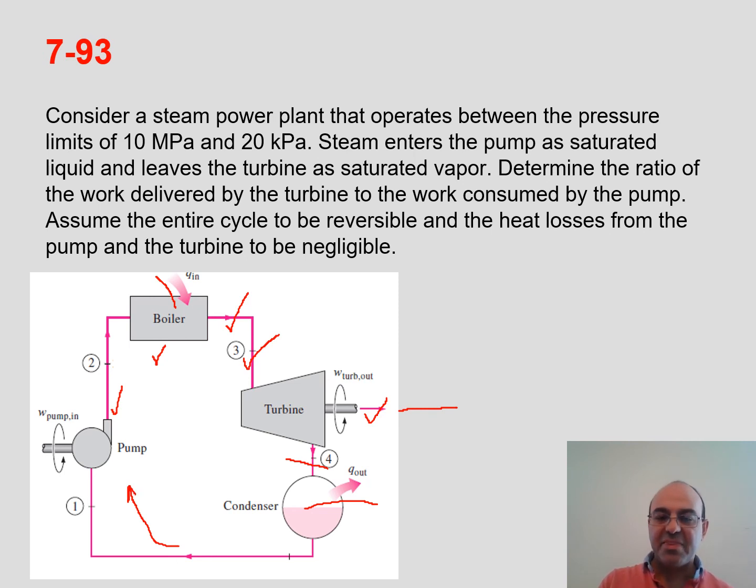The reason that we need to do this process is, first of all, we cannot remove this part because it's against the second law. It's not possible. Later you will see the cycle for this power plant and understand it better. But for now, in the pump, we can only pressurize a liquid. We cannot pressurize a mixture of water and its vapors. So that's why it has to be liquefied and then introduced to the pump. Okay. So this was an explanation of different components.